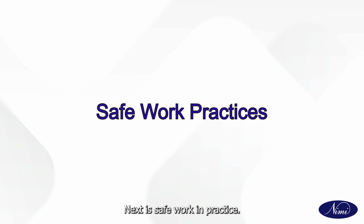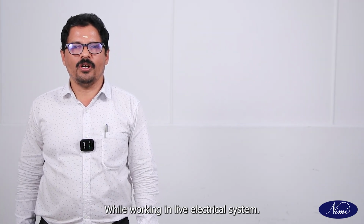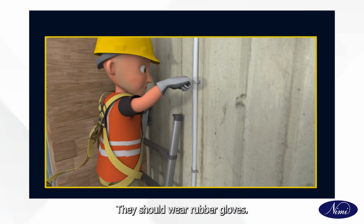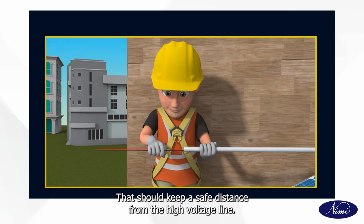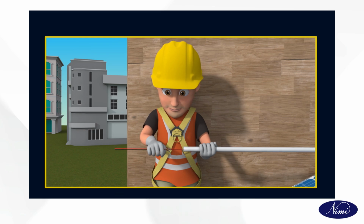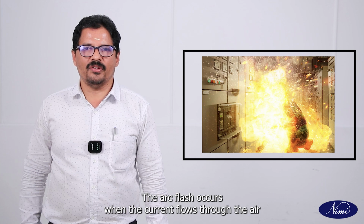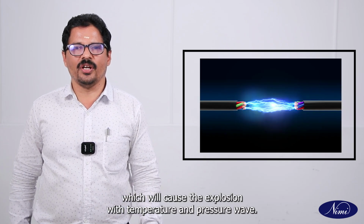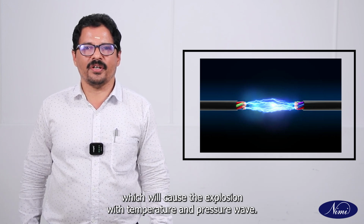Next is safe working practice. The worker should follow strict protocol while working on a live electrical system. They should wear rubber gloves. They should use only insulated tools. They should keep a safe distance from the high voltage line. Next is arc flash prevention. Arc flash occurs when current flows through the air between the conductors, which will cause an explosion with a temperature and pressure wave.